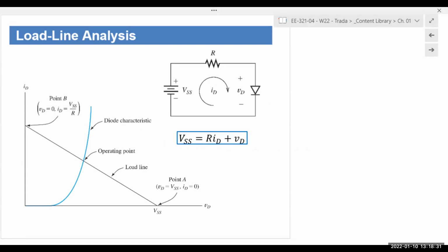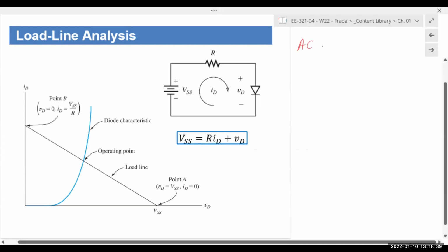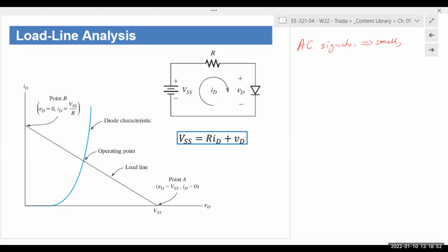So as I was saying, we have these signals that are very, very small. AC signals that are small and tiny. You could even use the word weak if you want. So we have weak signals and we need to make them stronger. We want to make them louder. So what do we do? We take these AC signals, we add them or modulate or multiply them with a stronger DC voltage, a stronger DC signal.